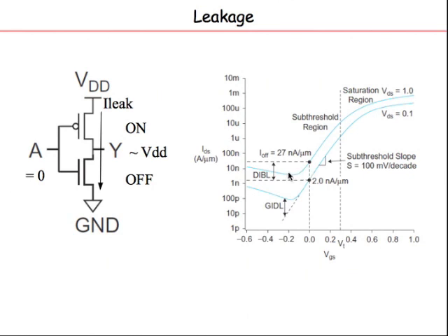At least DIBL, let's look at this. DIBL is drain-induced barrier lowering. What it is saying is that as I increase my drain voltage, even when there is no gate voltage, my current is going up. So somehow the barrier is reducing. Remember, I had the wall up to prevent water flow between the two reservoirs.